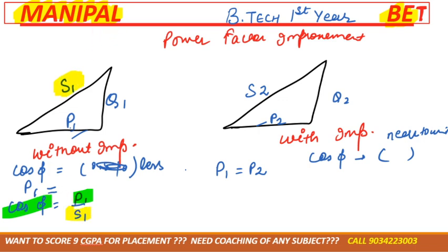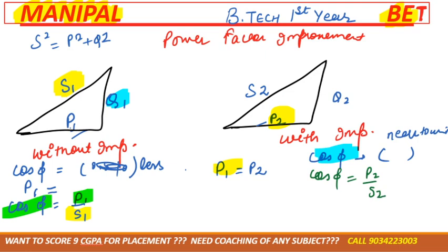With the help of S1 you can get Q1 by the formula S square is equal to P square plus Q square, correct? Then P1 is equal to P2, and again cos phi is given. Again we'll use the formula cos phi is P2 by S2, and get Q2, right? Ultimately, we'll need Q2 and Q1 only. Q2 minus Q1 is equal to V square...